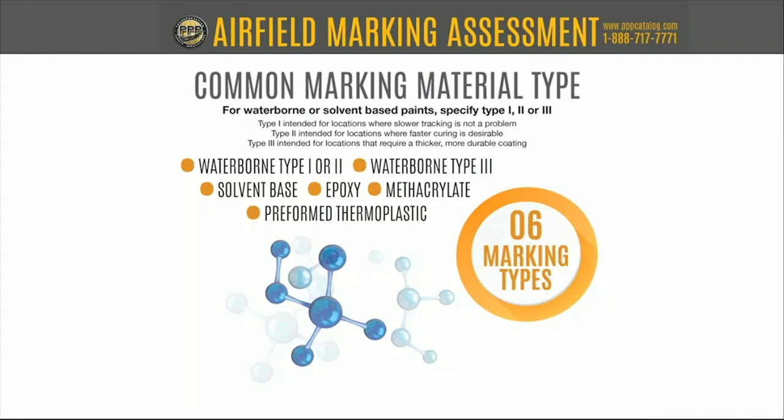Great. Yeah, I'll chime in on the same thing. Waterborne, just a couple notes. Waterborne type 1 generally doesn't retain beads well due to the resin that's commonly used, so be aware of that. Type 3 and some type 2 paints are designed, as Mike said, for this high build, and that high build will give you longer wear, and also you can get better adhesion of larger beads, which we'll be talking about in a few moments.